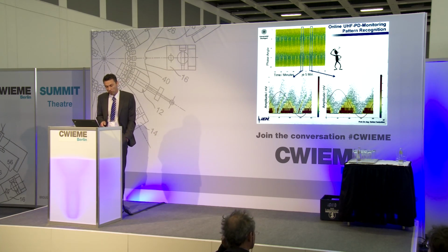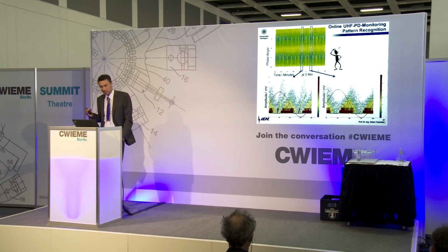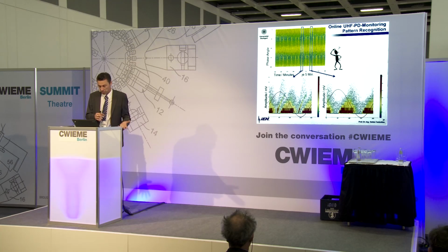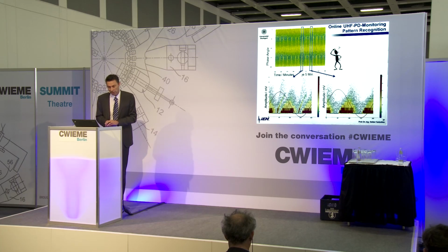Currently we are working on the interpretation of all these data, but you can see here that PD monitoring is problematic, not because of the measurement technology, this we have developed quite reliably, but because of the interpretation of the data. Of course, interpretation of the data you can only learn from data which you have measured, so I think it will need some more systems and years to gain the experience to interpret these signatures reliably.